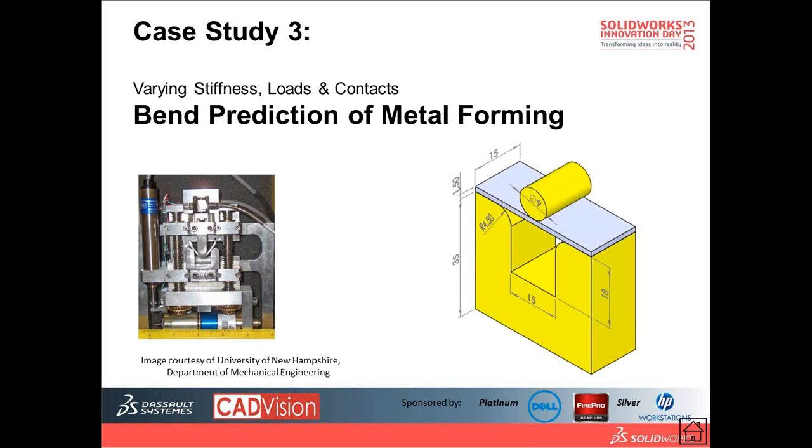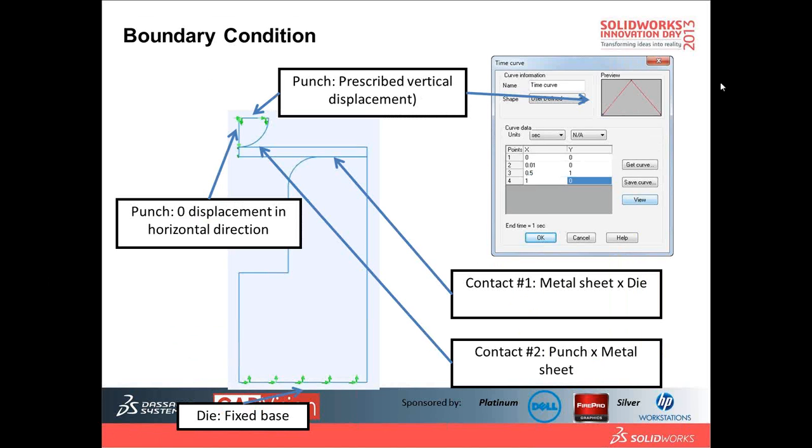So this is the next model. Actually, on the simulation side, we only need to prepare 3 things, right? So the point of interest here could involve many things, including how can I adjust the spring back effect when I push down and pull up? How do I get exactly, let's say, 45 degrees? Or how should I design the fixture? Is the gap big or small, right? And how deep should I punch in, right? So there is a lot of interpretation we can do with the result if we can simulate this thing. Okay. So these are some sample setups.